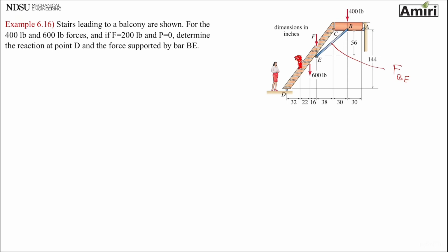Let me draw free body diagram. So this is, look at member CD. The force is at the end of it, but also there's a force F in the middle of it. Not exactly in the middle, but you know what I mean. So that makes it a multi-force or a 3-force. Same here. Nope, that's not a 3-force. That's multi-force. So as soon as you see one multi-force, that's a frame or machine. In this case, it's a frame. So I have to take it apart.